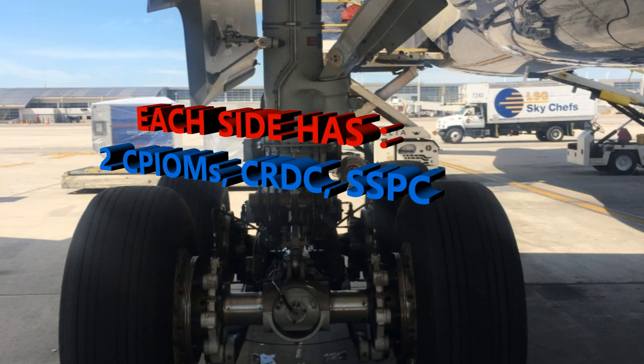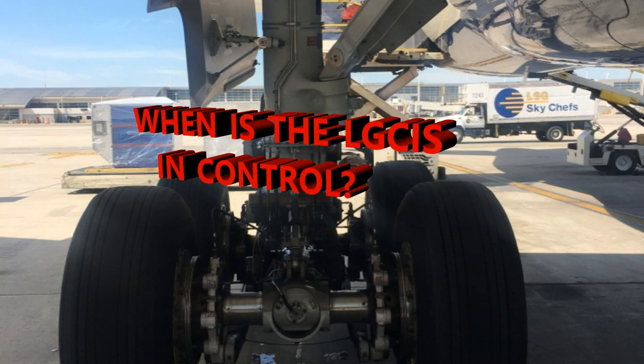When is it in control? When is this landing gear extension and retraction system in control? It's going to be in control when the selector lever is in an up position and the active side becomes inoperable.